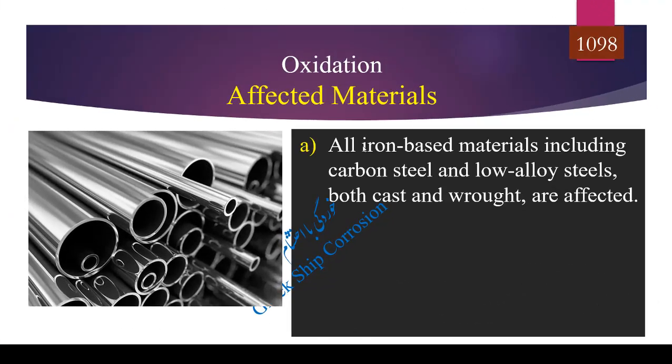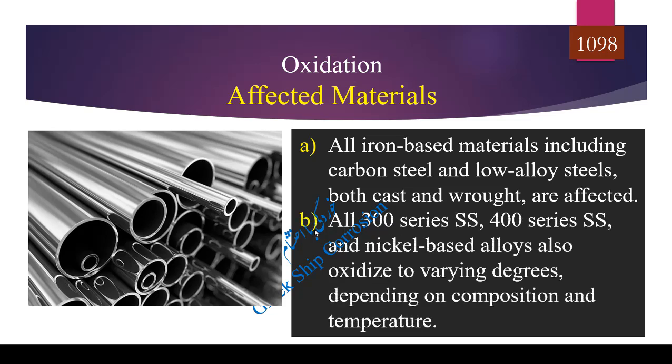Affected materials. A. All iron-based materials, including carbon steel and low-alloy steels, both cast and wrought, are affected. B. All 300 series stainless steel, 400 series stainless steel, and nickel-based alloys also oxidize to varying degrees, depending on composition and temperature.